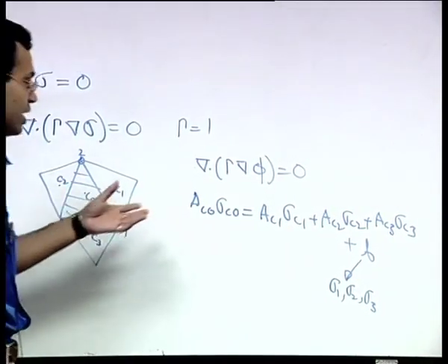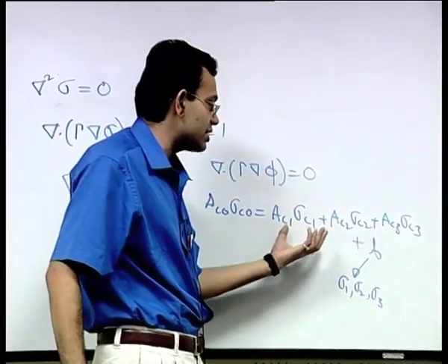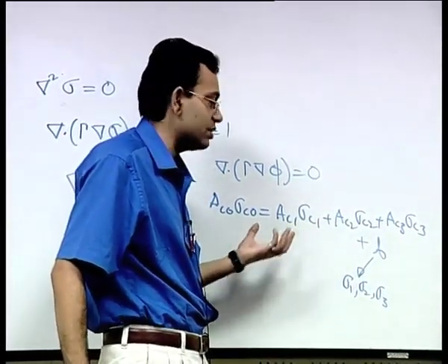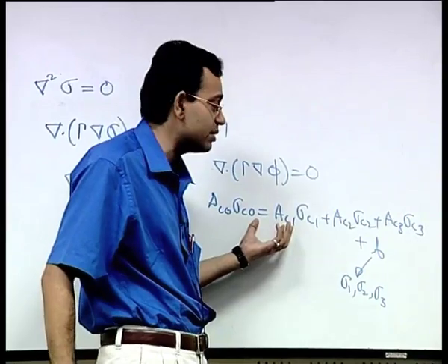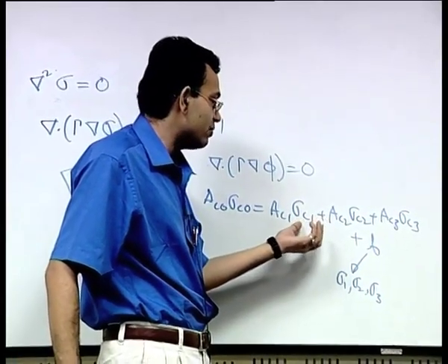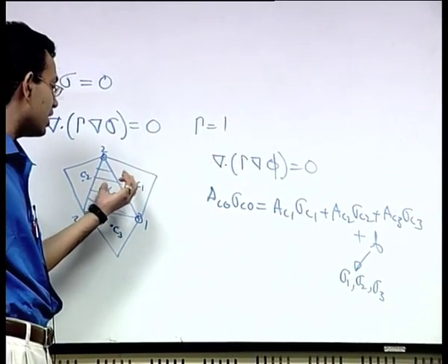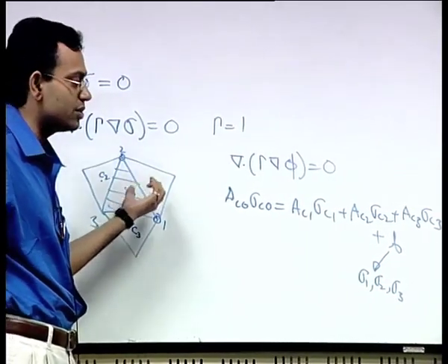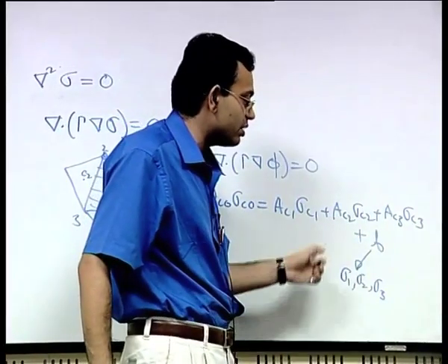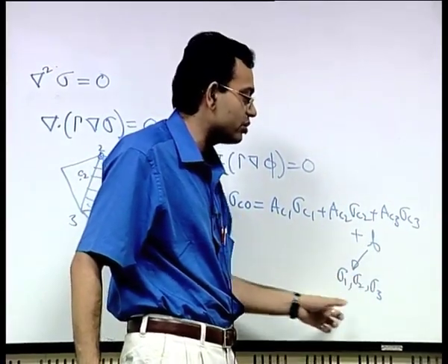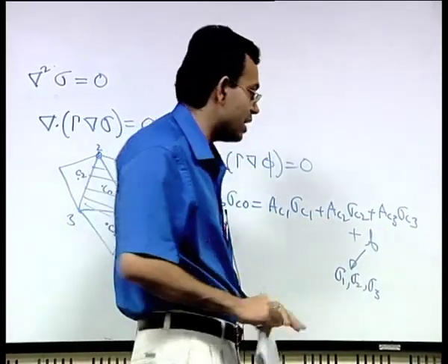So you can write it in a similar way as the standard diffusion equation for a structured mesh, where you have the values expressed in terms of the differences of the values at the centroids of the neighboring control volumes, but because of the unstructured nature of the mesh you also have some non-orthogonal diffusion flux which will appear in this.